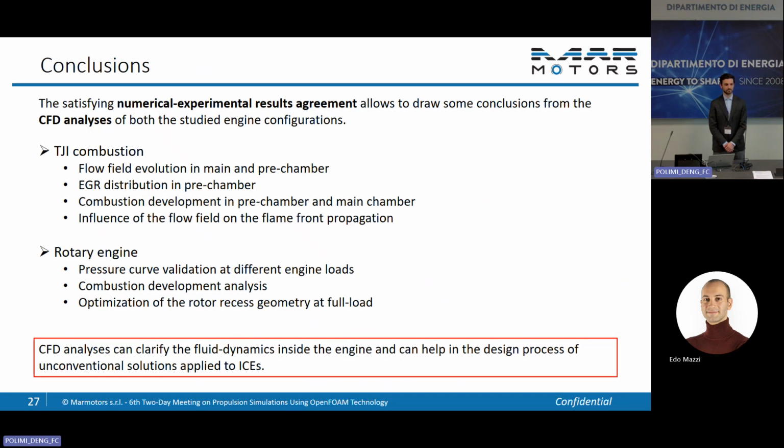Right? And then going back to another point, which is to the speaker, is heat transfer, considering the fact that inherently the rotor engine has a higher surface to volume ratio. Heat loss and flame propagation near the wall quenching, those are very critical issues in our experience. So I would like your opinion about your experience while working on this in terms of your combustion models to capture those aspects near the wall. Okay. Have you looked into that aspect already?